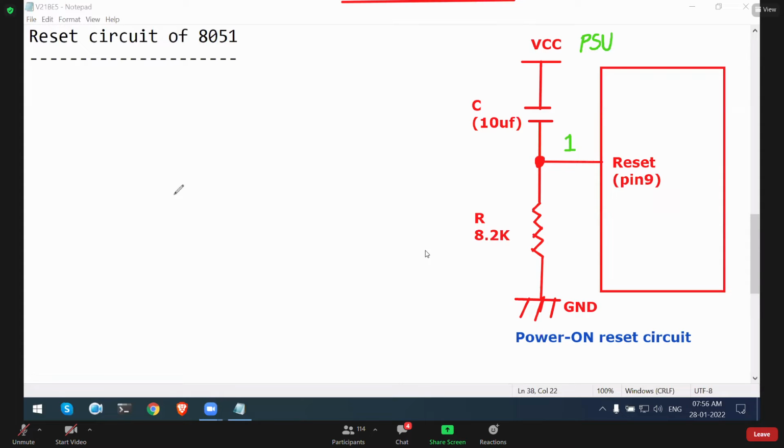So first of all, if your code size is greater than the flash memory size, then your program will not get compiled. And when you're compiling the program, if the compiler is allowing it, you should know the flash memory size of the microcontroller, and the compiler will show the size of your hex file also, so you can observe that. Whatever compiler we are using will not compile the program if the code size is greater than the flash memory size.